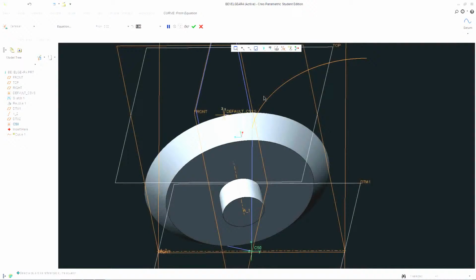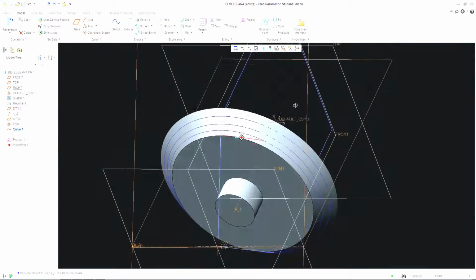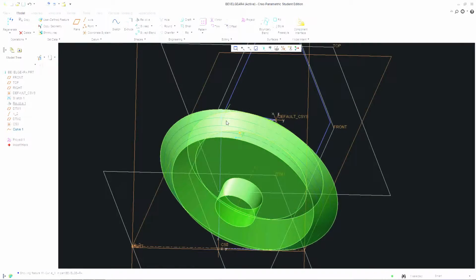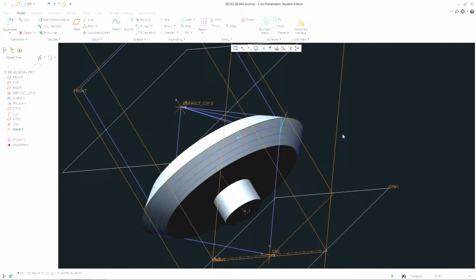And we don't want this curve to travel too long, so you can just go here and change the amount. I'll change it to 0.4, and that will cut it shorter. And there you go. Now we have an involute curve starting at the base circle.